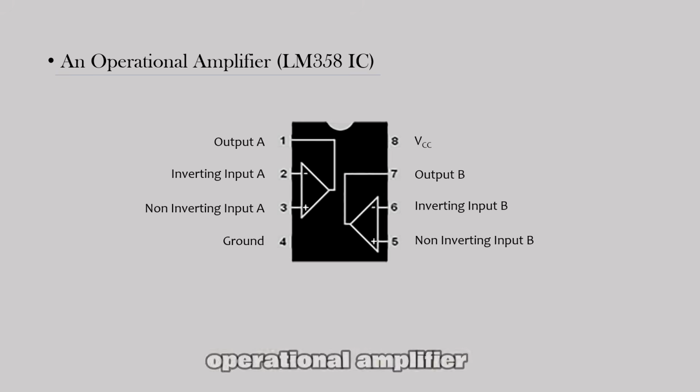So to use the operational amplifier, we supply the amplifier with voltage on its power pins. Okay, so we have plus V, we have minus V, and we can supply between 5 to approximately 30 volts across that pin. Okay, and we then bring in the voltages whose difference we want it to amplify on the inverting pin and the non-inverting pin.